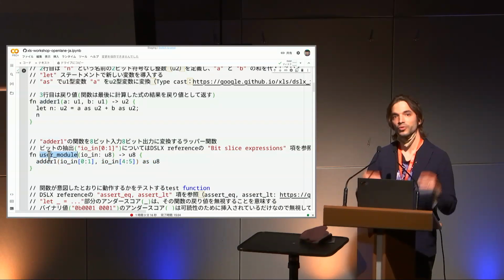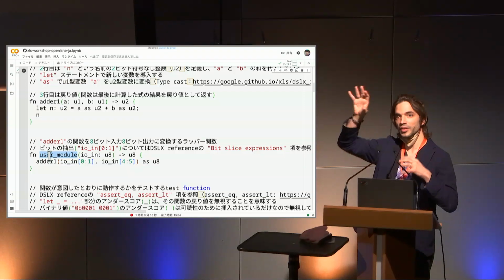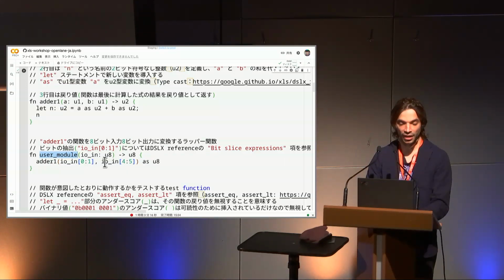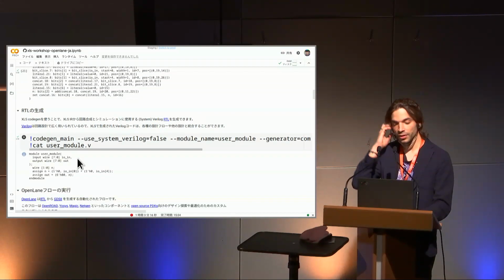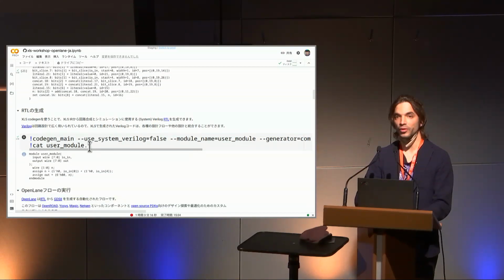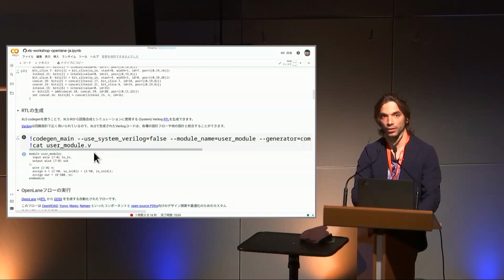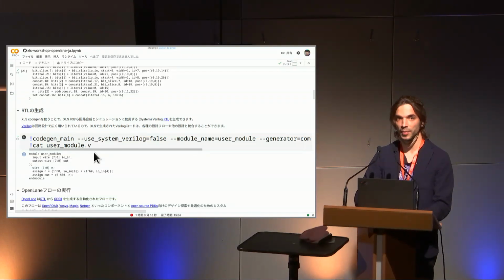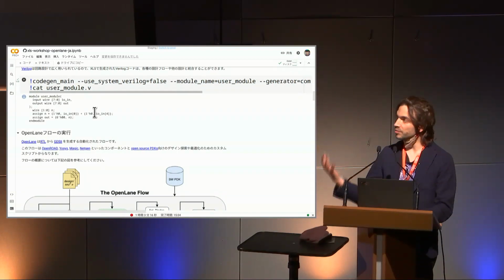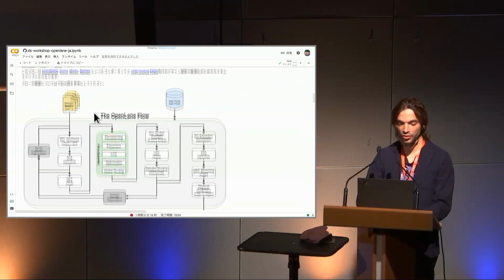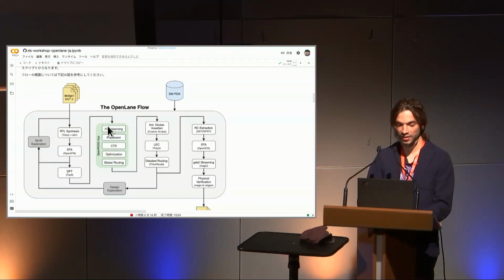And so here I want to make a bigger chip actually, one that has 8 inputs and 8 outputs. And I can define how those 8 inputs and 8 outputs map to my adder function. And so I can run this with a toolchain, get an intermediate representation, and start running it through the tool. There is a tool that converted it to Verilog, which is a different language that's more low level, that describes the relation between all those components, and that's compatible with the rest of the open source silicon toolchain. And then I can run it through a series of syntheses for floor planning and routing.